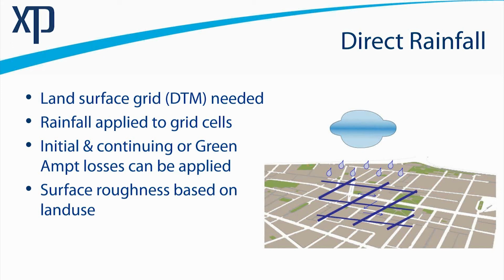All you need to do in a model then is bring that surface terrain information into the software, draw a polygon out to the catchment extents, and tell it to rain, and apply your design storm to a polygon, and storm data will then distribute itself, find the low points, and accumulate as it would, hopefully, in the real world.